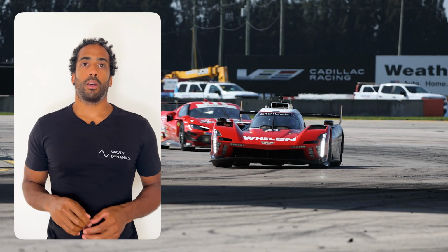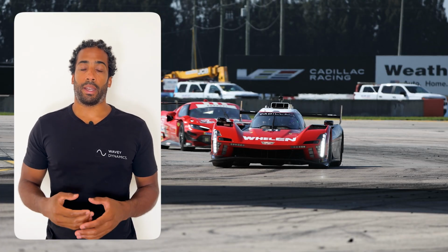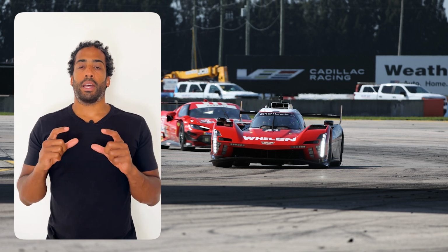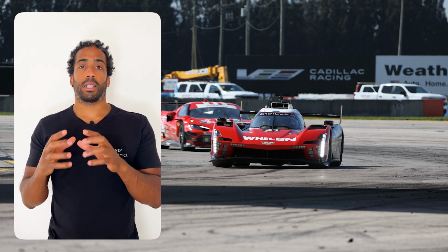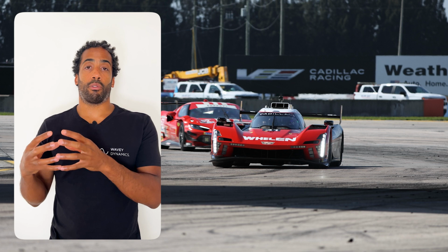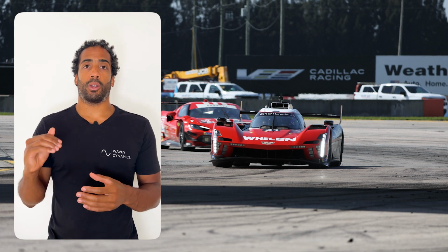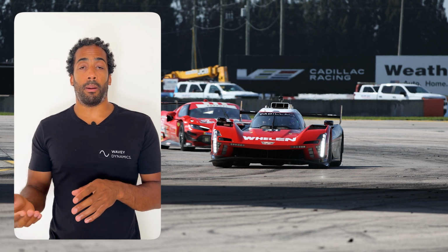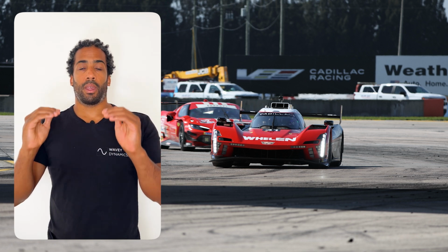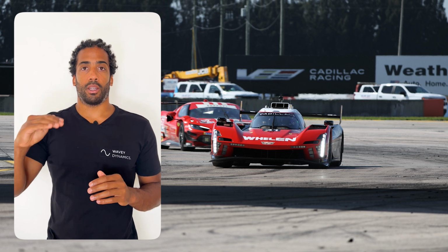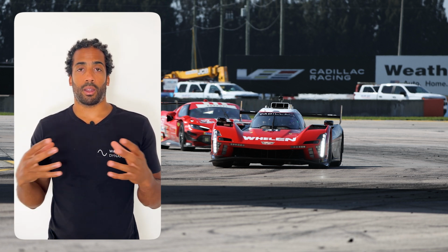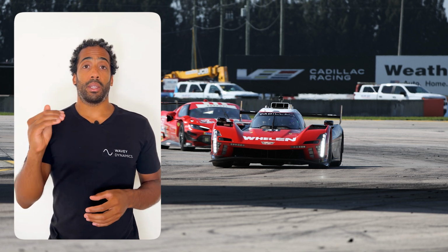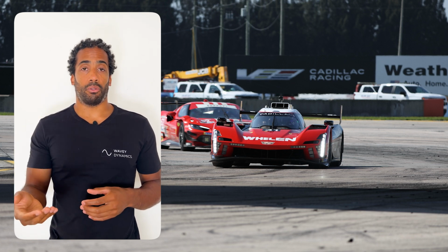Pause. So what do I mean when I say the ride response and the natural frequency are very different? The natural frequency is essentially a way to describe the rate at which a sprung mass oscillates in response to an input. So as I watch the car going over the bump, the body rises up and then there's some kind of oscillation as the body settles to its steady state value. The quicker this is, the higher the natural frequency is.